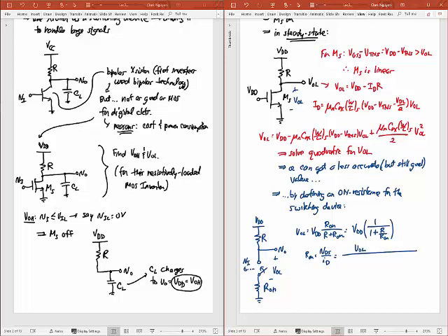I know what the current is going through the transistor because we've already established that the transistor is in the linear region. So I'm going to say that the current is mu n times Cox times all of this here, W over L sub S, times what I have across the transistor here, VDD minus VTNS minus VOL over 2, that whole thing times VOL.